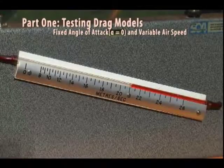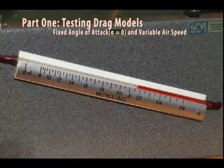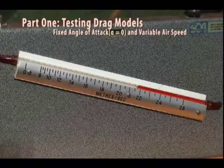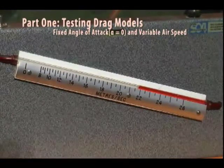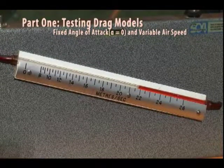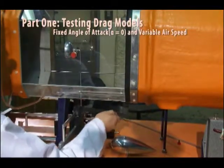For each drag model, repeat the test at different airflow speeds, ranging from 12 meters per second to 26 meters per second, with a fixed increment of 2 meters per second. Repeat drag force measurements for the 5 drag models using the same speeds. Don't forget to follow the same steps to set the model for testing.